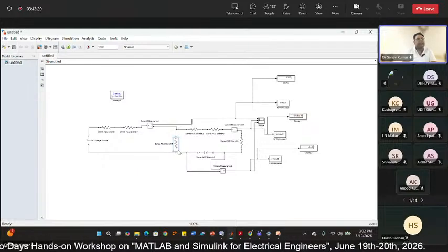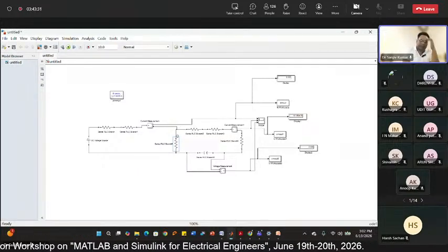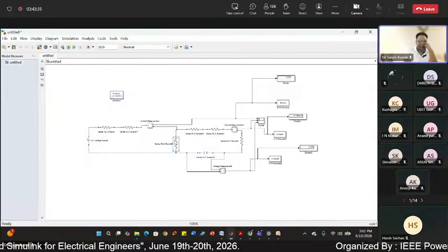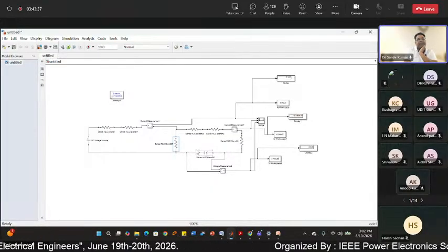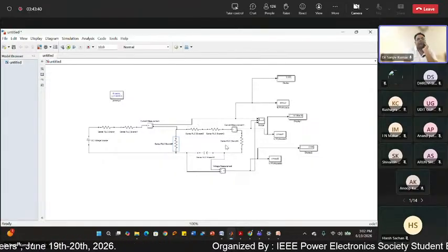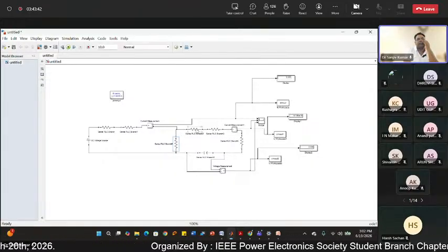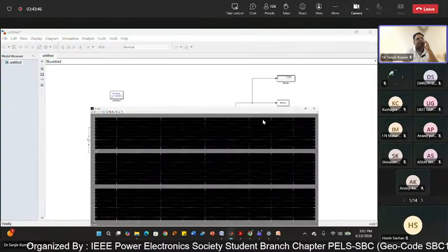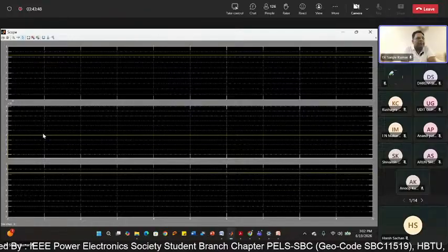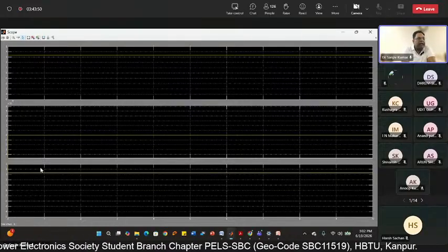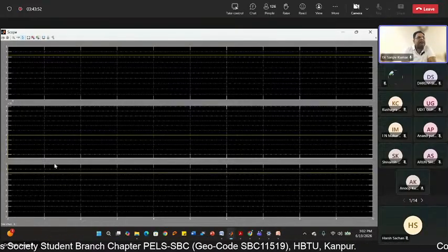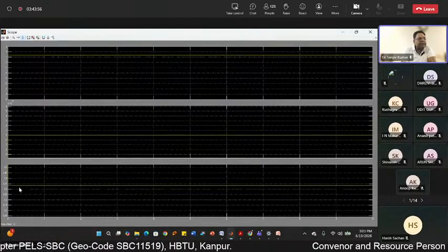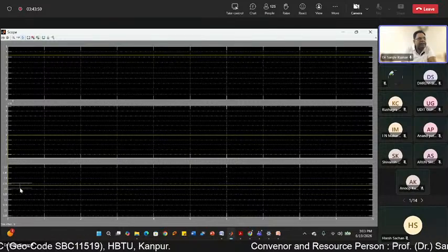That is, this voltage is 1 multiplied by 3.33. So this voltage is 3.33, and when the capacitor is charged up to this voltage, it will not allow any current to flow. Once there is no current, this value is 0. That is shown in the waveform. You can see the I2 current is 0, and this capacitor voltage is up to 3.33. That you can see here.